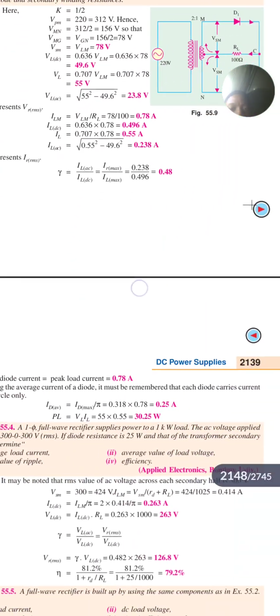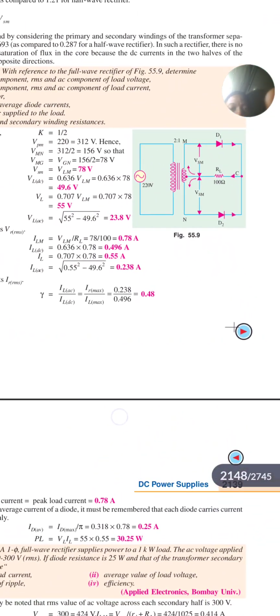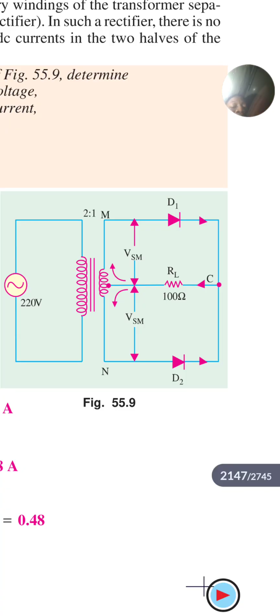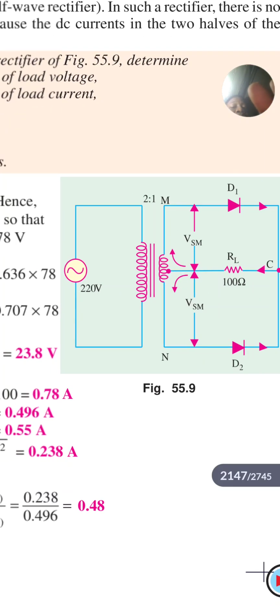These are the normal calculation. If there is time, I'll touch it. You see, from the look, you know this center tap stuff. This is the primary VRMS. You are going to divide this 220 by 2 to get your secondary VRMS. You now multiply that secondary VRMS times root 2 to get your VM. Let's call it VSM, but let's call it VM.